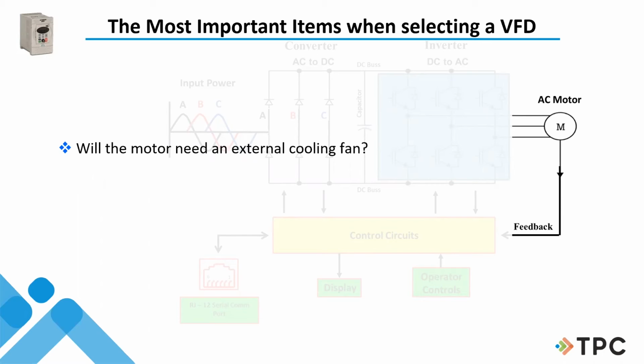Here it talks about external cooling. One of the things we tend to do, and a lot of manufacturers will tell you that, hey, if you buy this motor and we can speed it up or slow it down, you can get rid of a gearbox. Well, that may or may not be true depending on your load. So it's kind of back to knowing about that load again. And in some cases during a production run, you may slow that particular screw or pump way down low, where that 1800 RPM motor is only turning 900 RPMs or maybe slower.